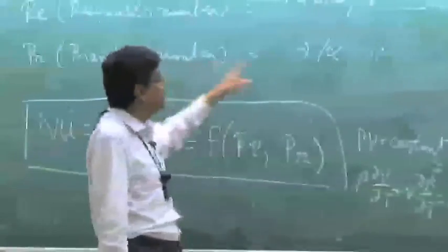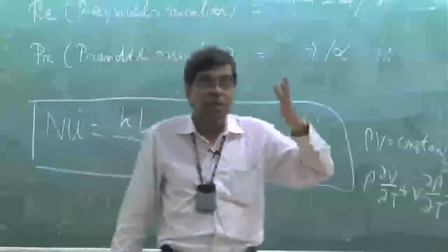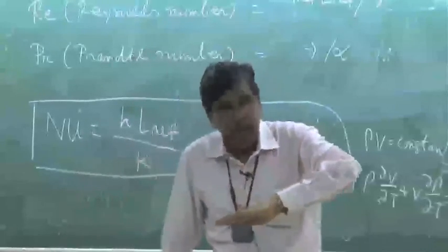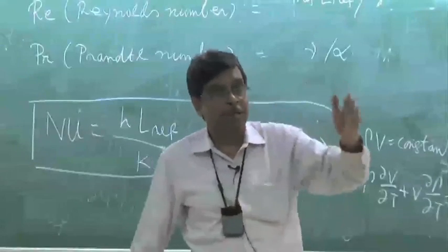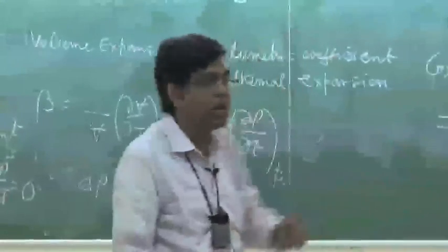And the physical significance of Prandtl number is the ratio of the two diffusivities, relative. That means nu is responsible for taking the momentum transport, the presence of the plate in the flow field. How much the presence of the plate goes to the flow field, what is the extent of hydrodynamic boundary layer.